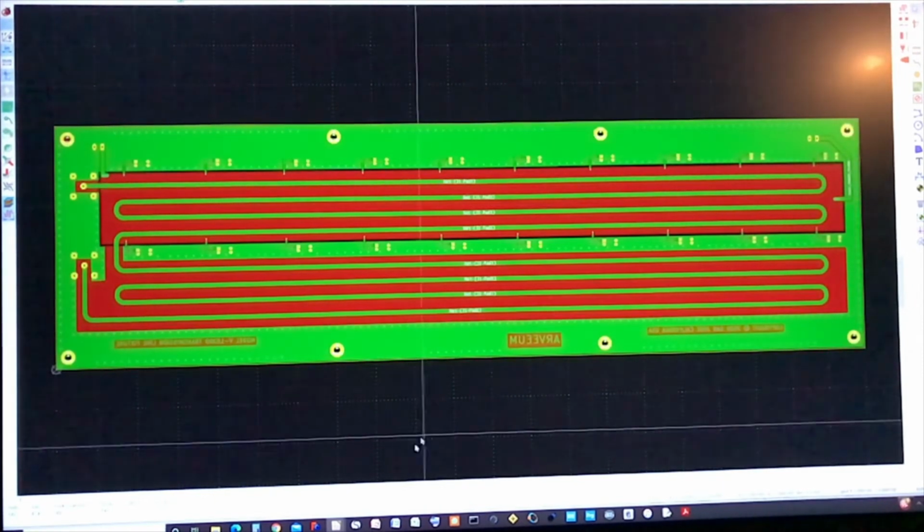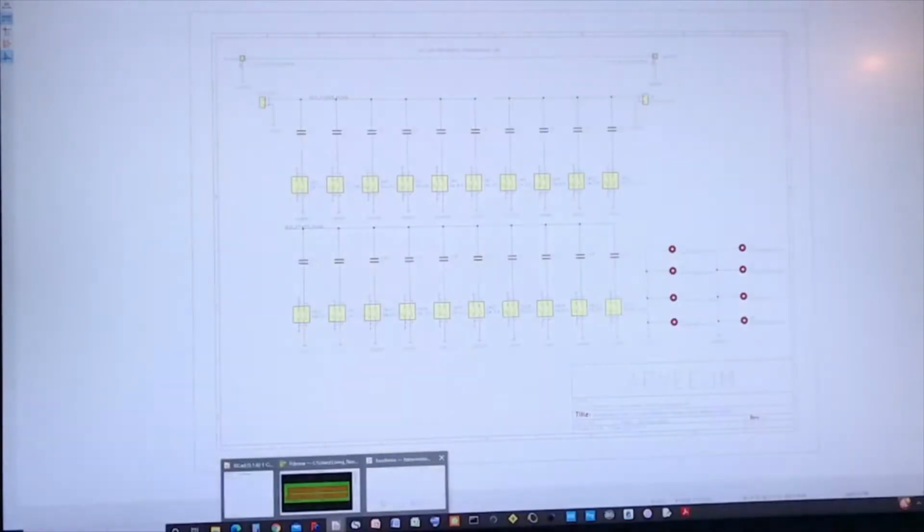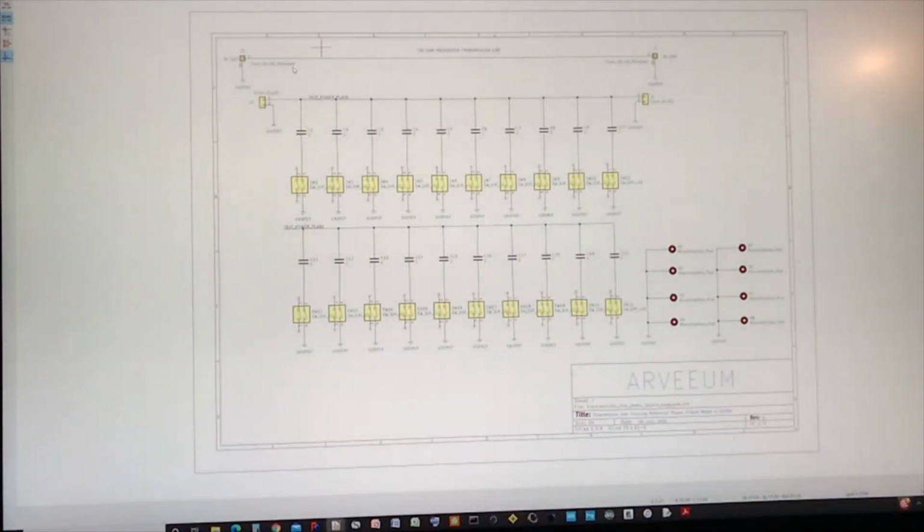The schematic for the board is this. So it's, like I said, a single microstrip line, 50 ohm, and it's 20 nanoseconds long. And here are all the caps that are connected to that reference plane that has a moat around it. And all the caps have switches, so all the caps can be connected to the main plane, which is the ground ref, by closing the switches, and you can do one by one, and that is the board.